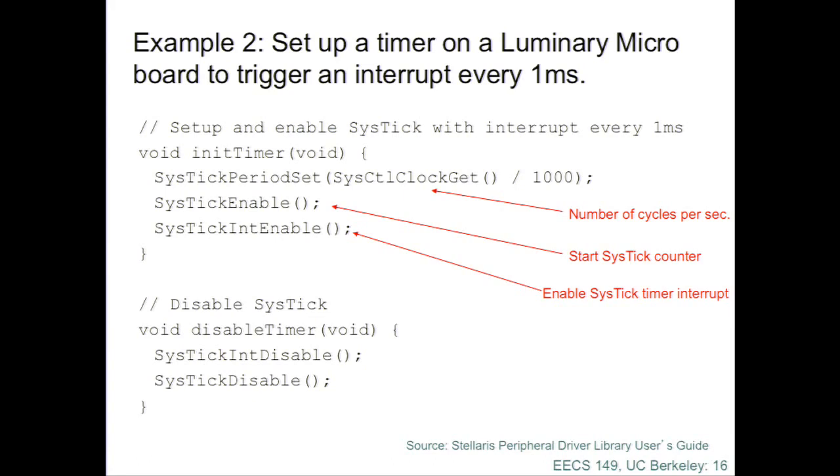They don't seem to think ASCII characters are so expensive. I can actually tell what that does from its name. It's setting up a timer to trigger a periodic interrupt. And they're calling that the system tick. So periodically, you're going to get an interrupt request. And how often? Well, this often. This returns the number of cycles per second, so every millisecond, you are going to get an interrupt.